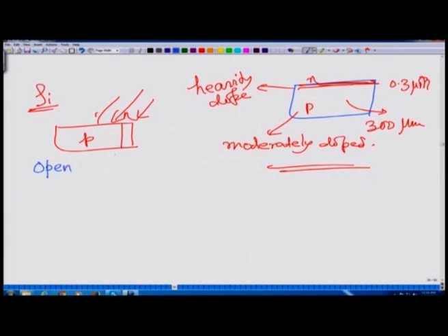Why open circuit? Because we have not connected anything, we have not made any circuit. This voltage appears between this side and this side, light is falling, remember, and the voltage appearing here is a result of recombination, new generations and some accumulation. That is typically, let us say, 0.06 volt or so.